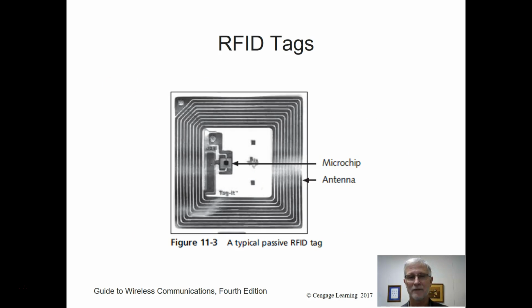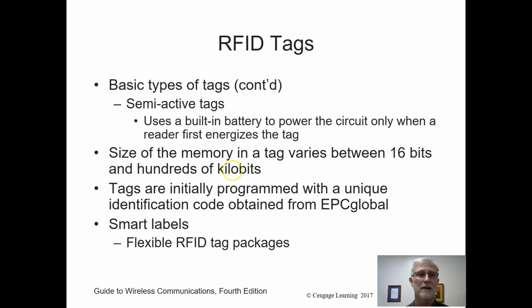And just to give you a rough idea, you've got a microprocessor and the antenna. As far as this is a passive tag that you're seeing here. Now, there's a third type that's kind of a semi-active tag. It's got a built-in battery, but you first have to have the reader energize it, and then the battery takes over to start it. So the battery will last longer, but definitely not as long as a passive tag.